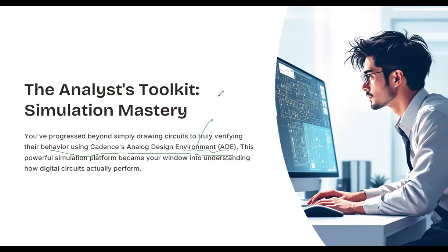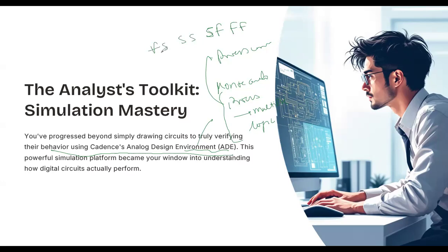And initially, when we started doing the Monte Carlo or the process corner on the multiple logics, we talked about the process corner simulation, where we talked about slow NMOS fast PMOS, fast NMOS fast PMOS, slow NMOS slow PMOS, fast NMOS slow PMOS.